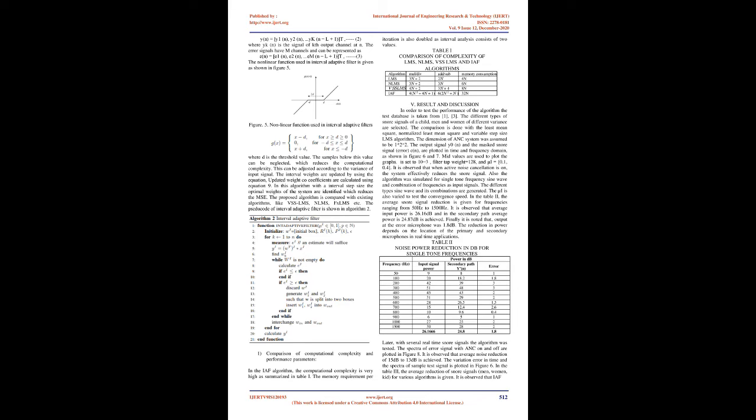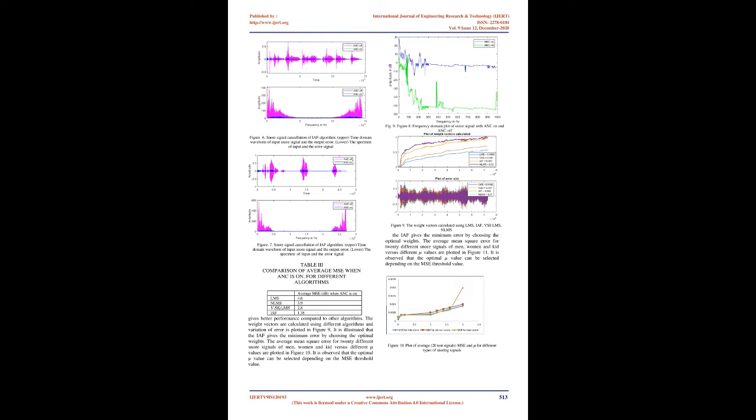In order to develop an algorithm for snore cancellation, it is important to examine the power spectrum of the snoring signals and also the frequency domain characteristics of all kinds of snore signals. In the literature [39], the power spectrum of the snoring signal is studied. Snore signals of men, women, and kids are analyzed. It is observed that the major power content is below 2500 Hz and the main frequency band lies from 150 Hz to 1500 Hz. In 1.3, the snore signals of men, women, and children of all age groups are collected.